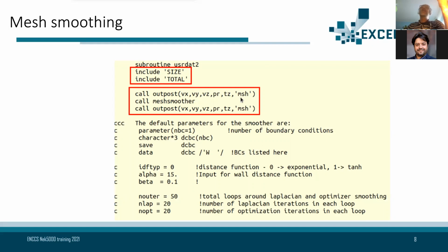You could leave this as 3 empty spaces, and then you will simply not change the name of the simulation. But what's important here is as well that those Vx, Vy, Vz, you have no access to inside user.f unless you add our global memory description, which in this case is include total.